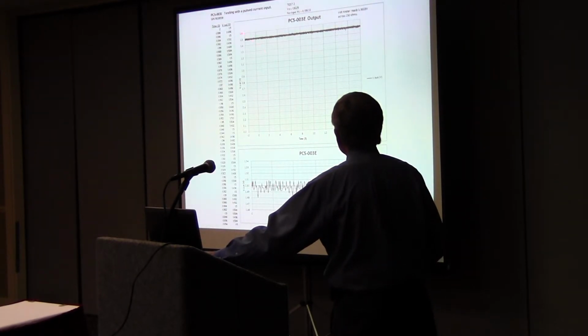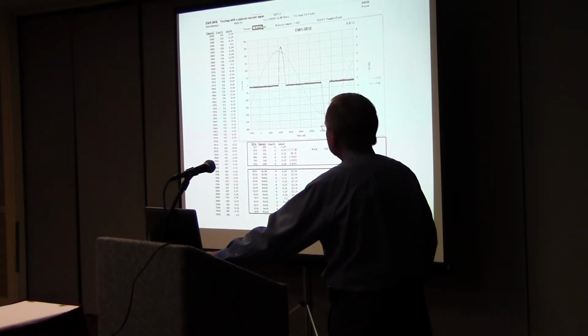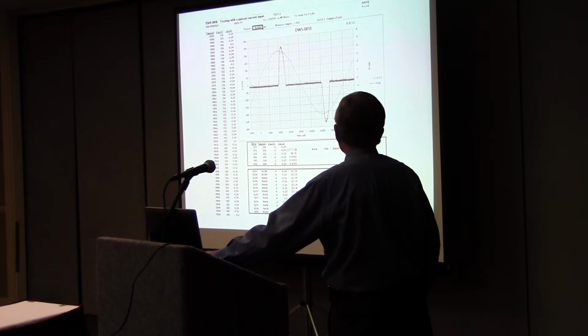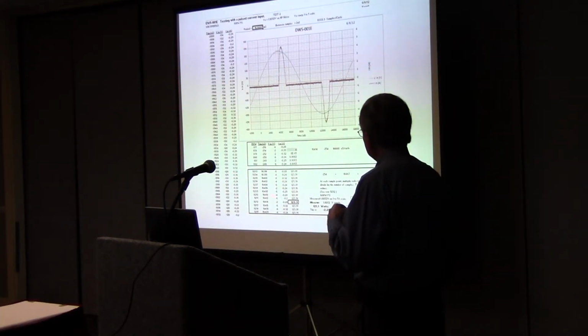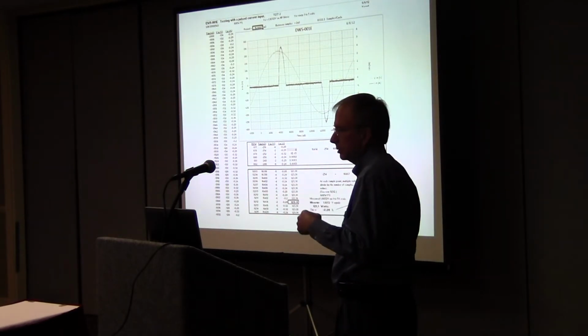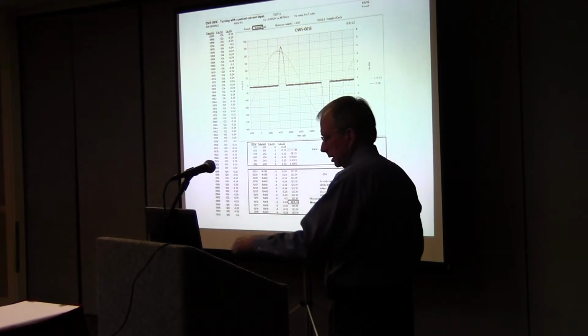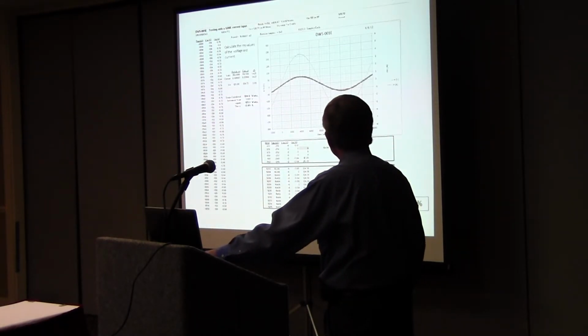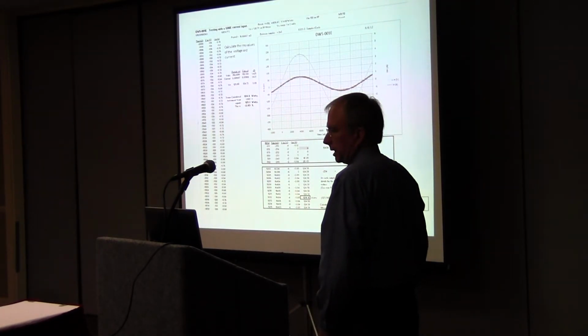And again, we looked at the output, none of this beat frequency business, just kind of high frequency hash that you quite often get. We did the same thing on the digital sampling. Believe it or not, we got about the same offset, and I'm beginning to wonder if the offset isn't something to do with maybe I synthesized the waveform just a little bit off. I might have had a slight offset in my calculation, because all the transducers that I measured were off about the same, minus 2%.